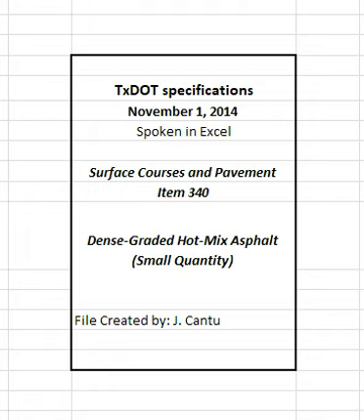4.3.2 Job Mix Formula Approval. The Job Mix Formula, JMF, is the combined aggregate gradation, target laboratory molded density, or end design level, and target asphalt percentage used to establish target values for hot mix production. JMF1 is the original laboratory mixture design used to produce the trial batch. When WMA is used, JMF1 may be designed and submitted to the engineer without including the WMA additive. When WMA is used, document the additive or process used and recommended rate on the JMF1 submittal.